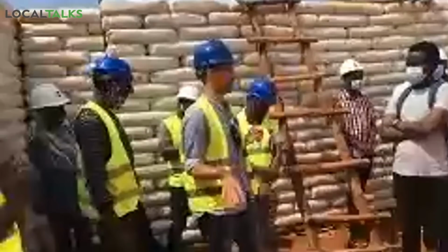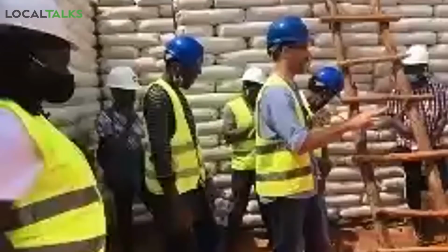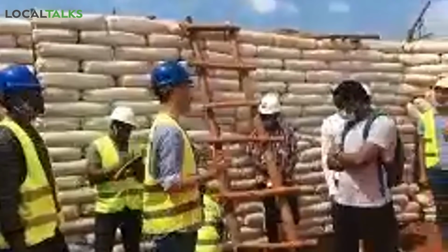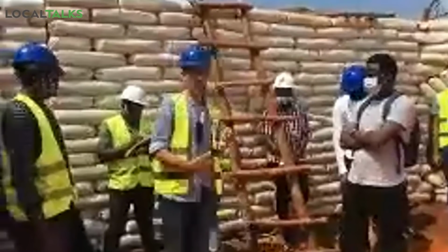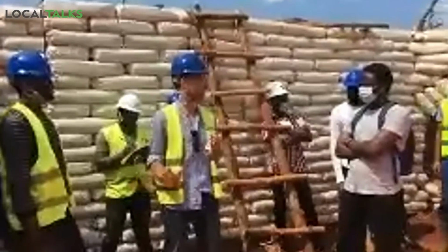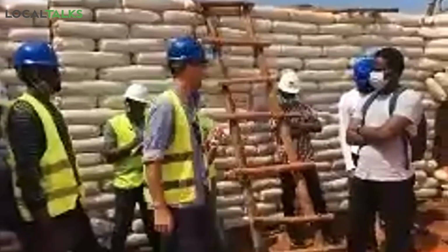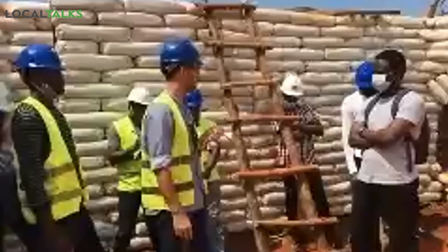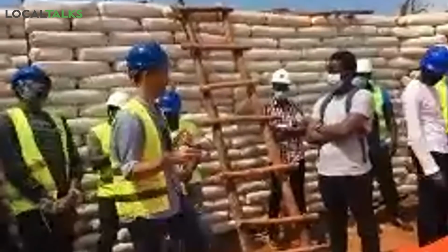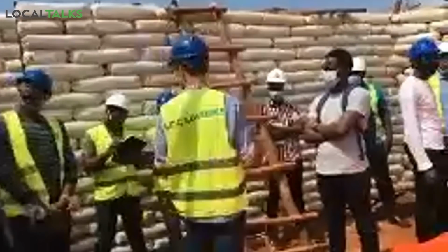Maybe one word about the floors. To protect it, we have an essentially dense concrete slab, and we ground it down so that the aggregate is exposed. And it turned out very, very beautifully. In the moment, it's hard to imagine, but by the time we are done with the primary work and can remove this protective sand, we actually only need to go once over with a polishing machine, and our floor is finished. Very sturdy, very long-lasting exposed aggregate concrete finish that really expresses the material in a very nice way.